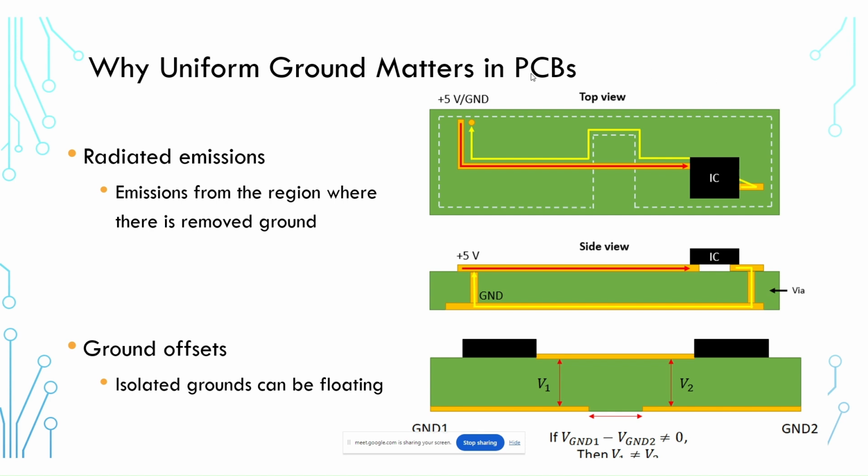Here in the top layer, what I'm showing is just a very simple board. And what I show here in this dashed line is the ground plane on layer 2. Now, as I mentioned before, if we send a signal into this integrated circuit through this trace, and this trace is routed over this slot, what happens is eventually that return current has to return through this ground plane.